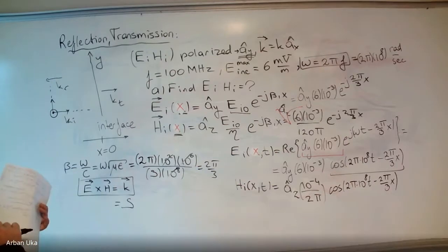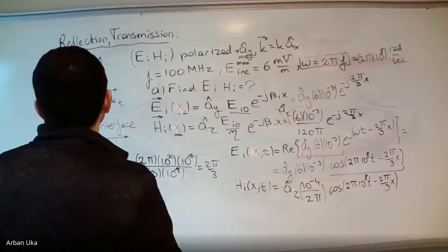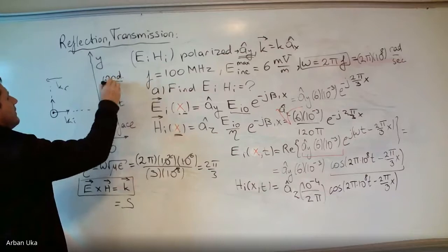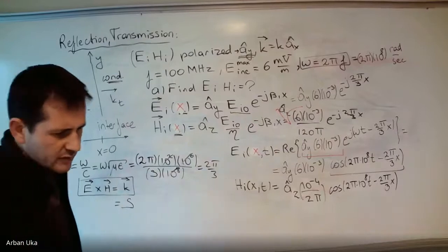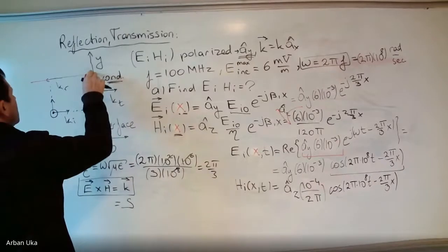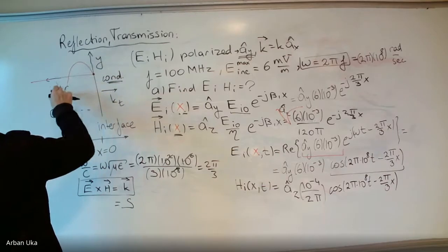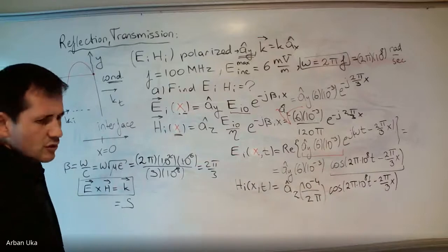Now, regarding the reflected wave: first of all, since this is a conductor, no wave is going to be transmitted. We just have reflection backwards. At this moment, we can also state that we're going to have a standing wave. Then the electric field intensity at the conductor is going to be equal to 0, and the magnetic field intensity at the surface is going to be maximum.